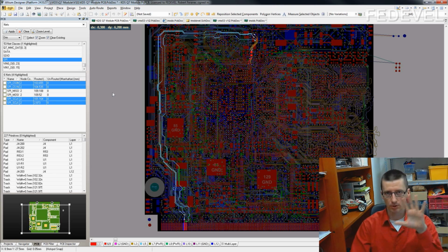And when all the local connections are connected, everything what left are just very simple nets, usually one wire nets or something very simple like LEDs or power management, you know, which switch on, switch off, power supply. These signals are not usually important. You can use as many layers as you need, as many wires as you need. You can fit these kind of tracks anywhere where is space in your layout.